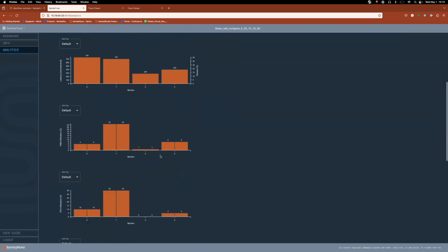And it will show you that by section. Now, one of the things that you're also going to want to do, remember how I said previously, if you're greater than 90% PCU utilization, you might want to break apart your sections some more. That doesn't mean that you want your PCU utilizations to be down to 0 either. You want to try to consume as much of the PCUs as you can per section to really drive and optimize your utilization of the chips.